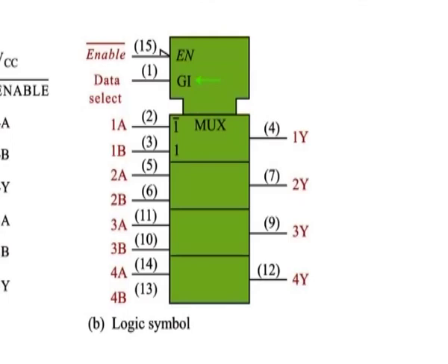In other words, when the data select input is high, the B inputs of the multiplexers are selected, and when the data select input is low, the A inputs are selected. A G is always used to denote AND dependency.